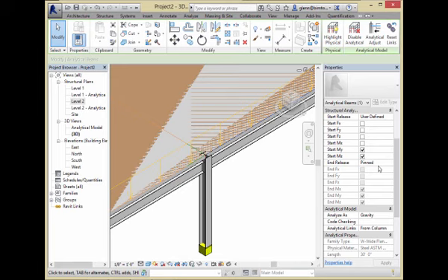The way this is going right now, if you think about the way that I define this by default, the columns are anchored in concrete. They're not moving. Everything up here is just pinned. So all the stress is really getting carried down to that big fixed connection. That's why we have these big moments in the columns. But if I started locking some of these connections up here, you'd have a very different profile because they'd be absorbing a lot of that and it wouldn't get torqued down to the bottom. So right now, our columns are carrying a lot of sideways stress because the only lateral resistance is coming from the base. And that's not a good design, but that's what it does by default.